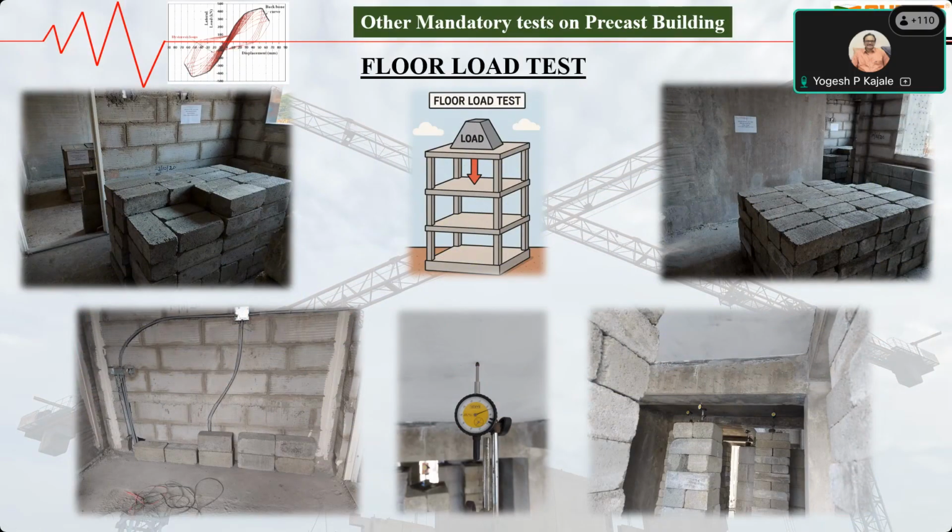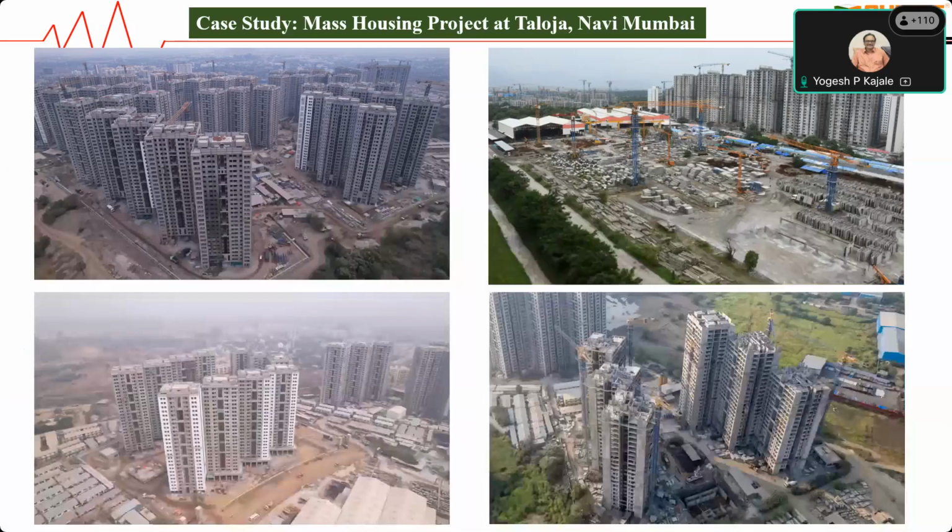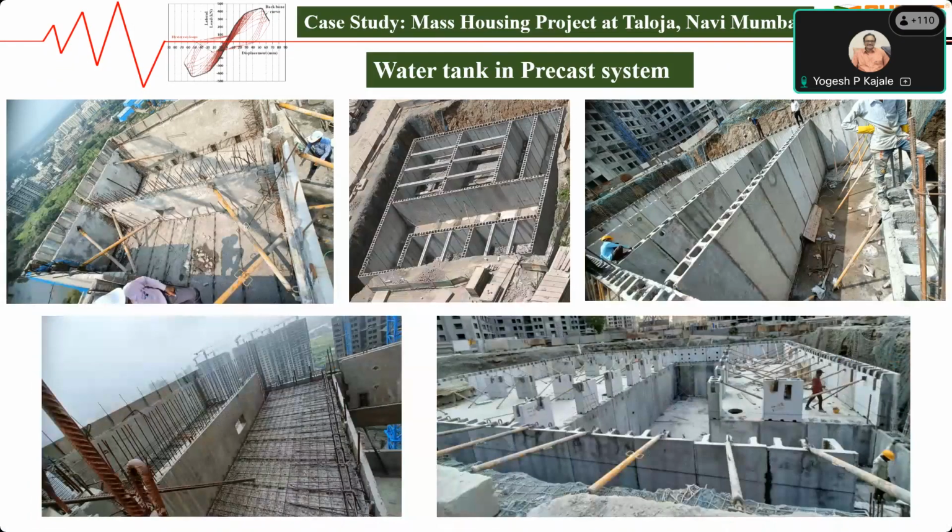Apart from the structural assessment, other load tests are also carried out on projects during construction, and those are typical floor load tests. This is of course a vertical load test, then the water tightness test that is essentially required to be conducted on every structure.